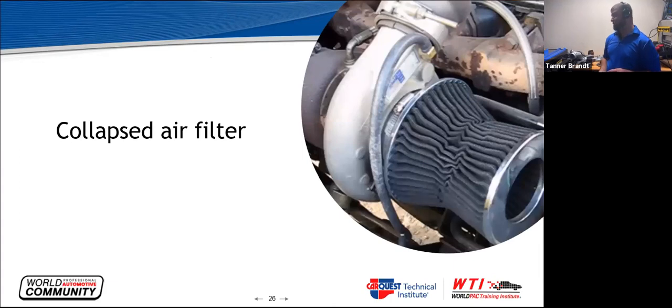All right, this is where it starts to get pretty neat. When an intake restriction happens on a vehicle, whether it's on a non-turbo or a turbo, if you were to put your hand over the intake of a car and step on the gas, you would pull that whole intake system into a vacuum, because the engine is a vacuum.